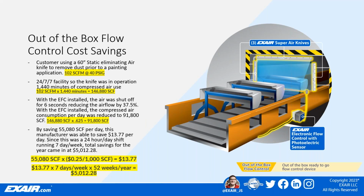So, a manufacturer of car bumpers was using a 60-inch Super Ion Air Knife supplied at 40 PSIG to simply remove dust that was statically clung to the part prior to a painting operation. The bumpers were moving at about 10 feet per minute and had varying amounts of space between each part. On average, the bumpers are only under the blow-off for around 10 seconds, while 6 seconds pass with no part present. With a 3-shift operation, this translated to 1,440 minutes of nonstop compressed air usage per day. So at 102 SCFM at 40 PSIG, their current method was totaling over 146,000 standard cubic feet.